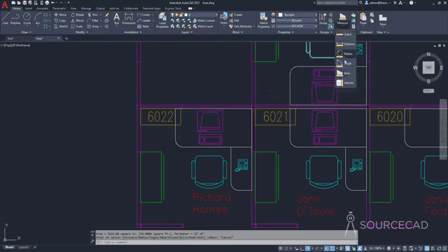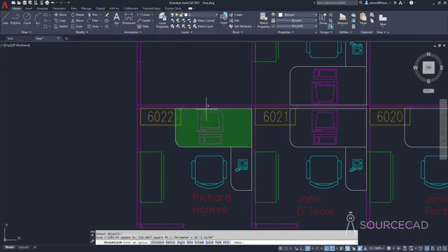I'll select area, and now instead of selecting 4 vertices, which we cannot for this one, just go to this object option. Now click on the object and the area will highlight in green, and we can now see the area here as well. So the area of this part of this table is 2102.64 square inch or 14 square feet, approximately 14.6. So that's the way of finding area using this area command.